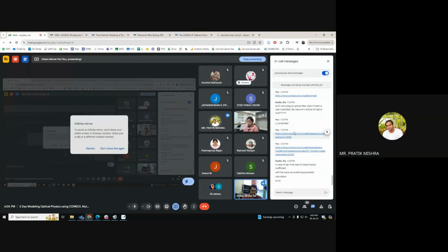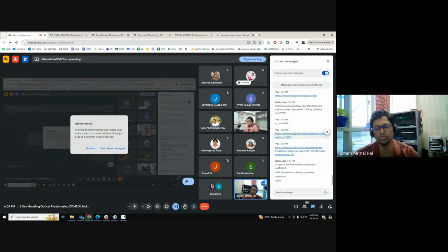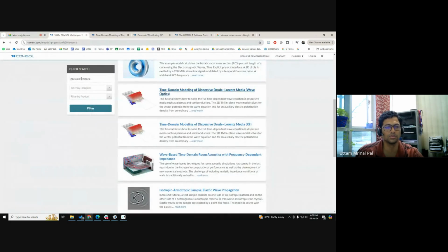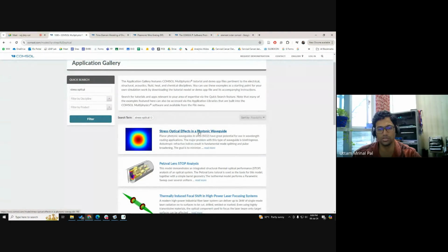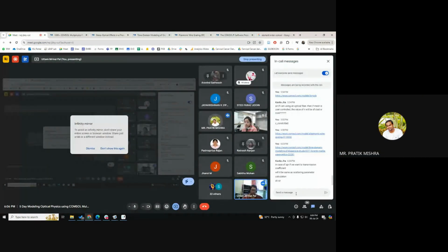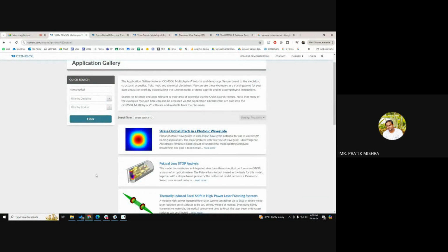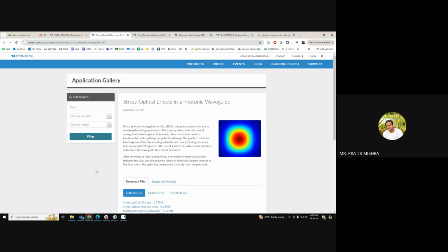Hello, sir. Actually, I have a question. Can we add two multiphysics, like stress and wave optics? Yes, you can do that. One of the examples is a stress optical fiber. I can share that, it couples. What physics do you want to couple? Wave optics and stress. Okay, so this is the example that you can couple. Here they have used PML and defined some refractive index based on the bending.